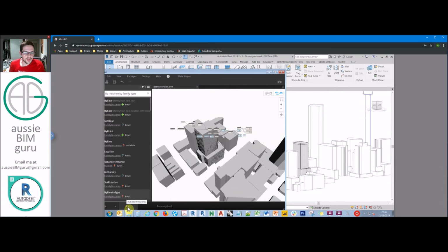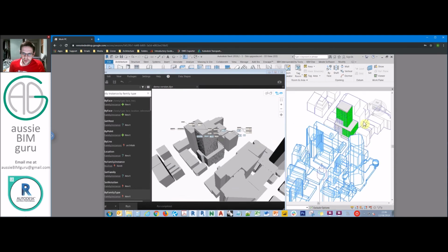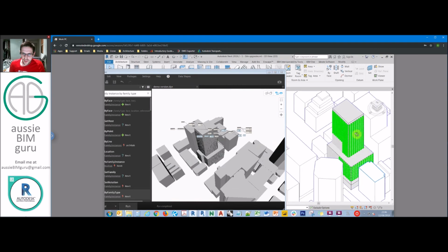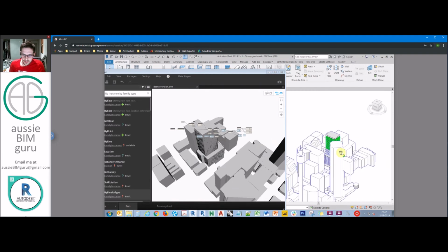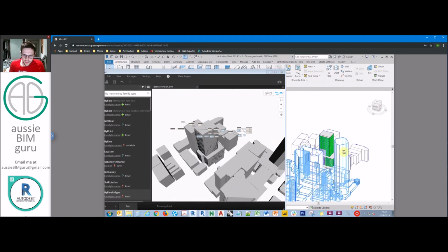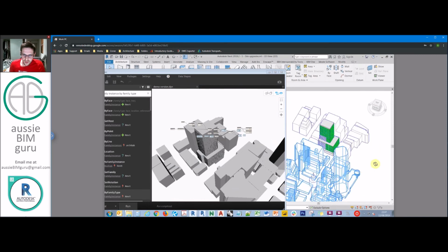Okay, so I'm just going to run my script now. And I should expect that my sensors will be told whether they can see the tower or not. And there you go. You can see that my sensors have received the data, and I can see that these particular elements can't see the tower, which is sort of what we'd expect because of this building that's in the way. So you can make sense of that result by lining yourself up with the building.